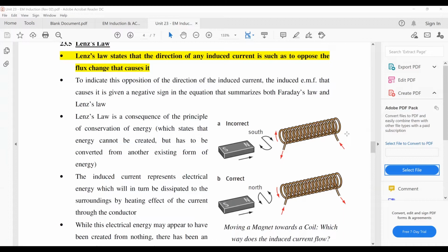If say I have a coil and I have a magnet, you know just now from the previous example, if I were to push it in, I would have EMF induced, I would have induced current, right? Because like here, before I put it in, I do not have flux linkage in the coil. But once I put it in, now I have flux linkage in the coil. I actually have change in flux linkage over a given time. There's rate of change of flux linkage.